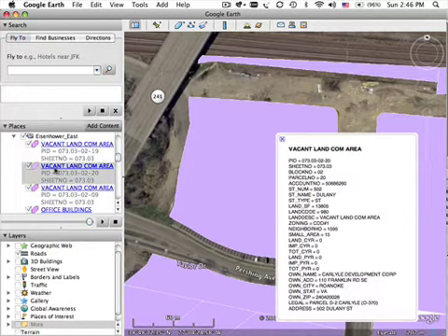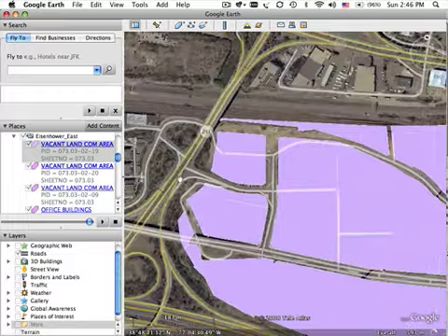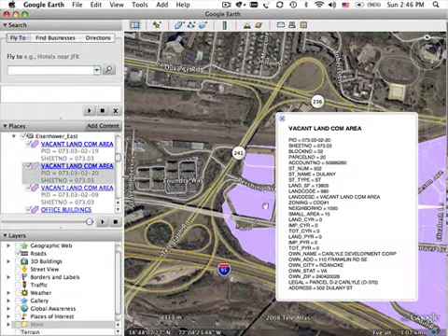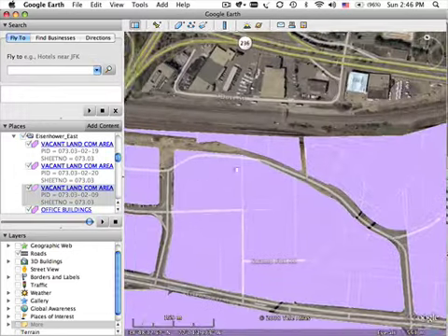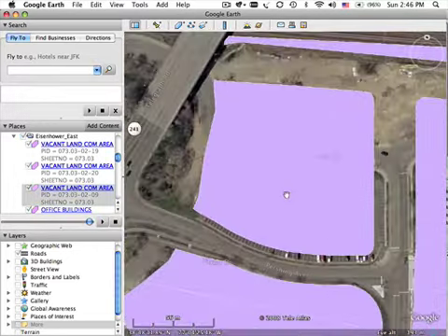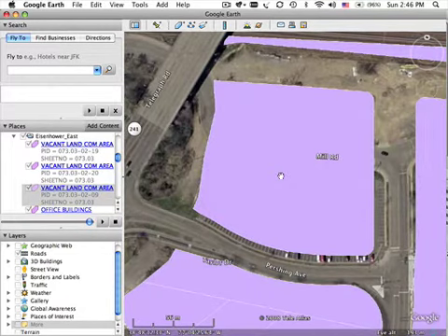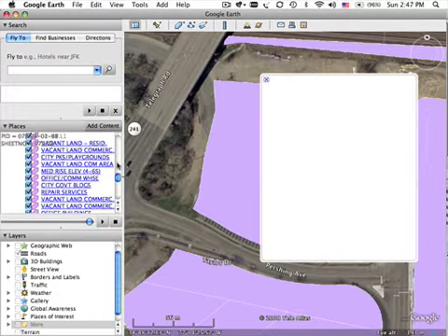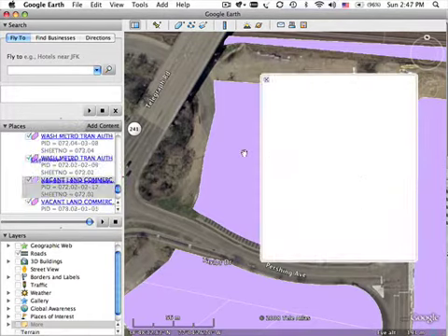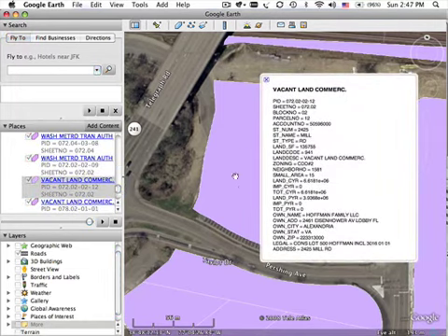This actually has individual parcels and data associated with them. So this is pointing to another parcel off screen here. Each of these is a parcel. The way in Google Earth that you actually grab a specific parcel graphically is you zoom into that one and you select Option or Alt, and it brings up that parcel. And highlights it on the left side as you click it.